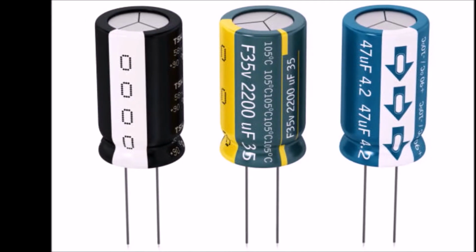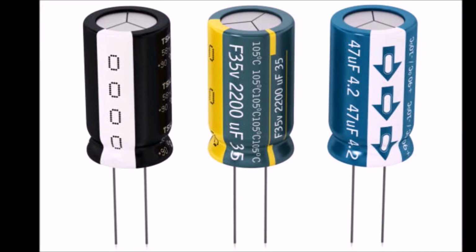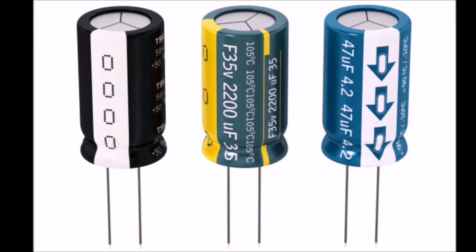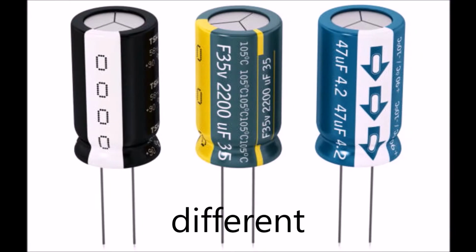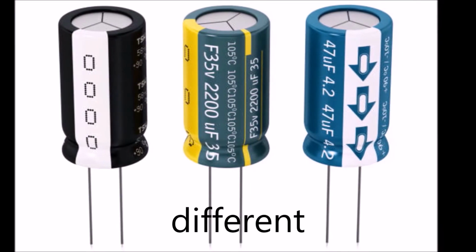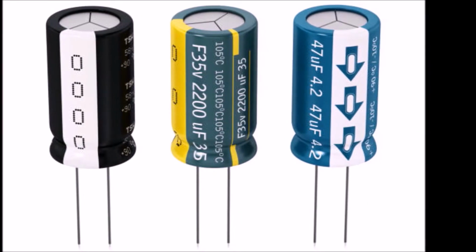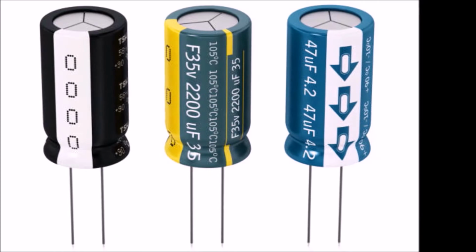In a perfect world, where two transistors or two resistors can be absolutely identical, the circuit would initialize itself symmetrically. But in reality, there's always a tiny manufacturing difference among resistors and capacitors, causing one transistor to start conducting before the other. As soon as that happens, the circuit is out of balance, and it starts to oscillate.